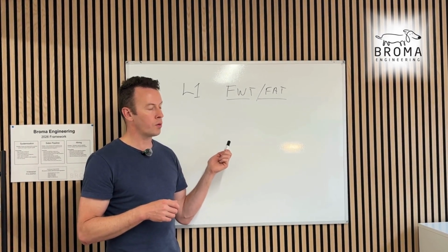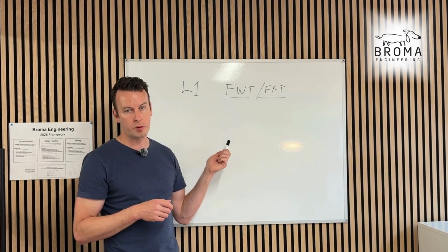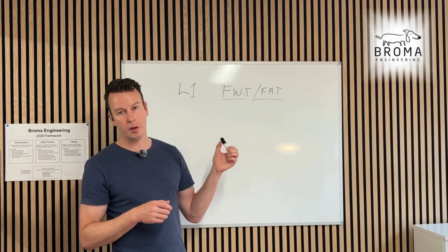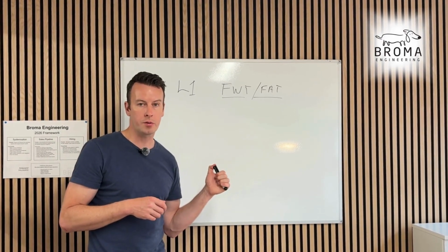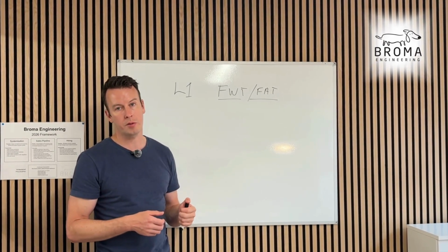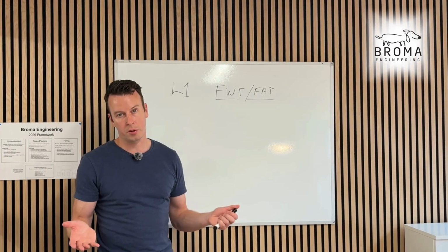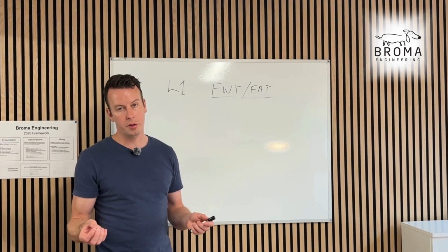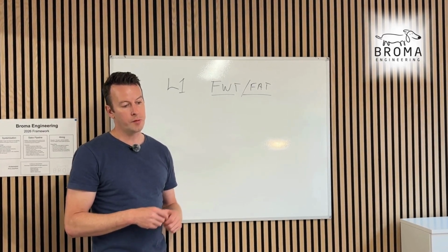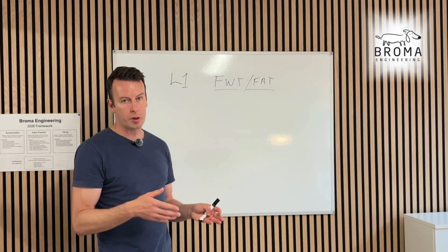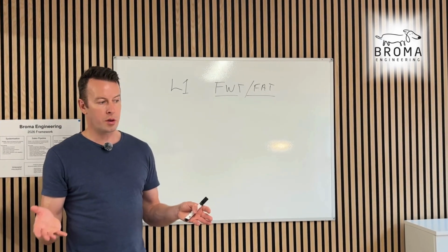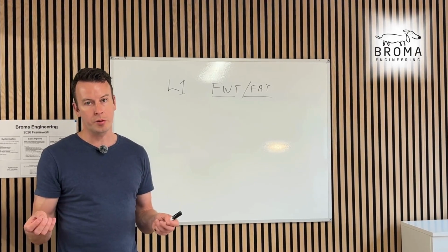You need to know where it's being dropped off, who's taking responsibility, who's unloading on site, where the trucks are going to, are we craning it onto the roof, are we sliding it into a room, do we need to leave some of the facade off, do we need to take some of the steel work down, do we need to tell the structural guys that we need special connections in the structural steel in order to remove panels, do we have to close the building up because it's the middle of winter and then open it up again, are we putting a special door in, a temporary door, or is there a door in the facility that's big enough to roll the equipment in all the way?